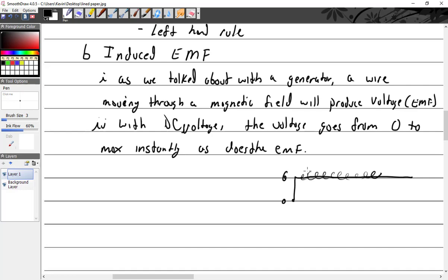The wire then has electrons moving. It's movement. It's a change. So the change builds up the magnetic field as it's expanding. It stops the electrons from coming in. I don't want you coming in. But once it's built up, it's there. And there is no counter EMF because there's no change. All right, I'll explain this more, but hopefully you can kind of get that. When voltage reaches the max, counter EMF stops. So that's kind of what I explained.